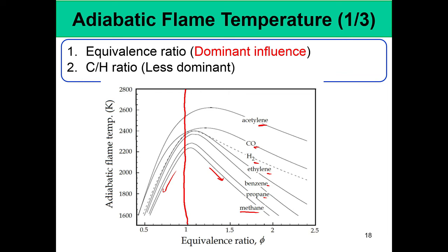Because now a lot of the energy of the sensible enthalpy is spent in heating up the unbound fuel. Of course, you do not have unbound fuel as such, but you have carbon monoxide and hydrogen, which are also fuels actually. So, a lot of the energy is now spent in heating up carbon monoxide and hydrogen when you have fuel rich combustion, as we have seen in the equilibrium composition calculation. And so the adiabatic flame temperature basically goes down on both sides of the stoichiometric condition, right.